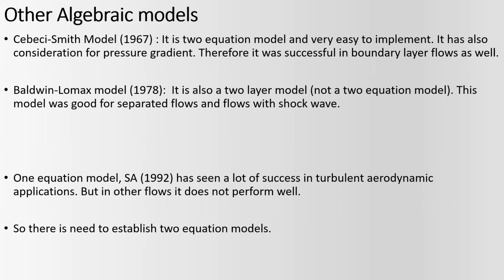Okay. After that, for your information, there are the K epsilon model and K omega model. The K epsilon model is an older model, and K omega also. They were also invented in the 1970s. But they had problems. Once they were modified and improved, they became the go-to models, but at that time, back in the 70s, the Baldwin-Lomax model was very famous.